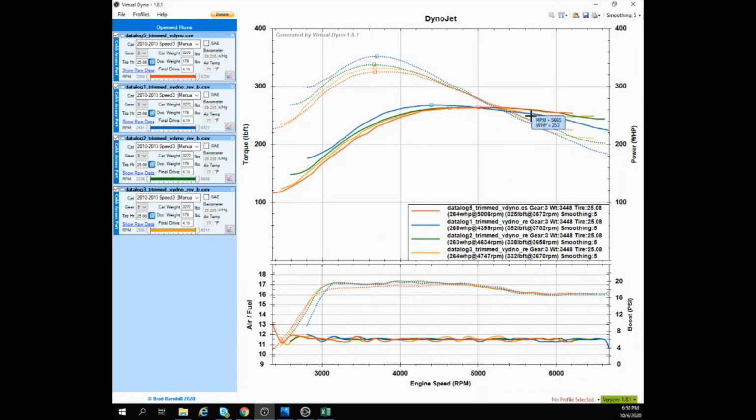But again, the reason we're not putting down over 300 horsepower, for example, is look at how our torque curve decays here, right? So once you get a big turbo and you're able to hold that boost pressure throughout the RPM band all the way to red line, you'll see this curve. The torque will get flat, and since horsepower is just a product of torque and RPM, that will get over 300 as well, and it'll increase all the way to red line. So that's kind of more the power you're used to on naturally aspirated cars, with a more linear power band. This is more dramatic. It comes on quick and it leaves quickly, but it's efficient. Your turbo spools easily. There's pros and cons of both.